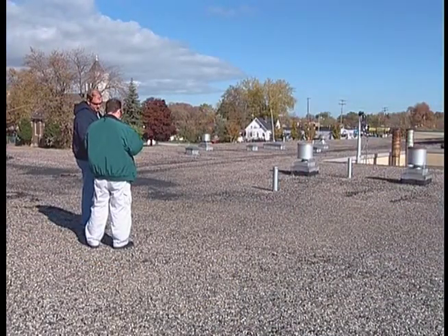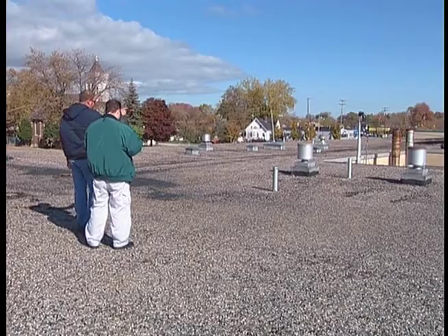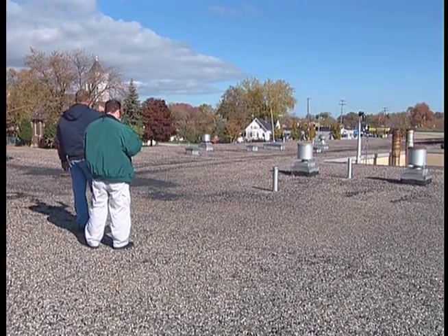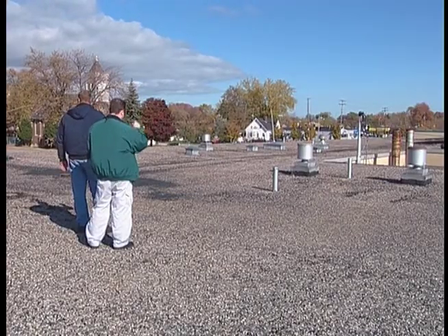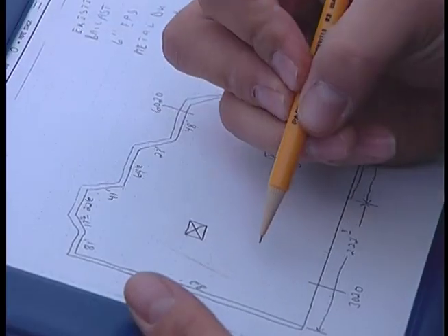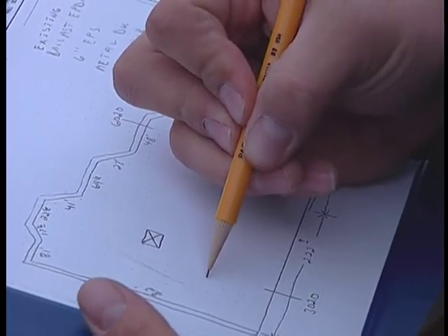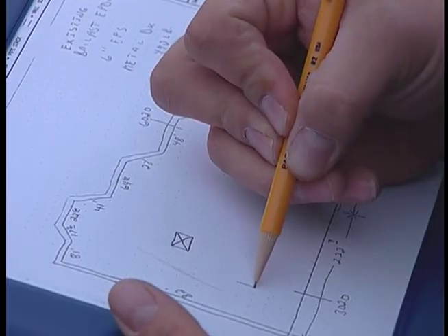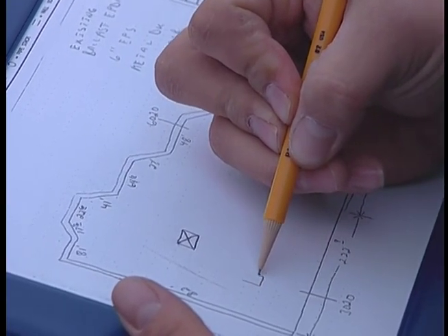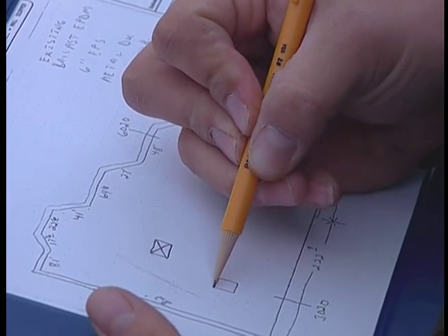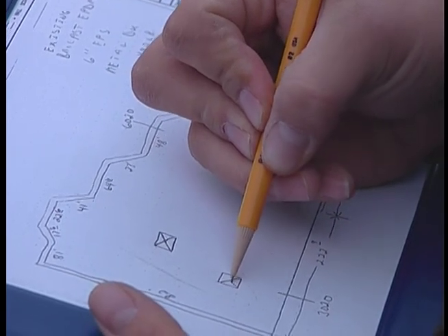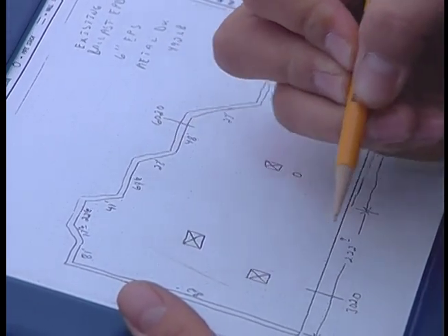Start by sketching the roof outline onto a Duro-Last grid sheet. The sketch will represent all items to be considered for quoting purposes and should account for all parapet walls and roof edges. As you measure the roof, sketch in and measure all penetrations that may be breaking the deck sheets. These are break points where deck sheets will be started or stopped, and field welding is required at these locations.